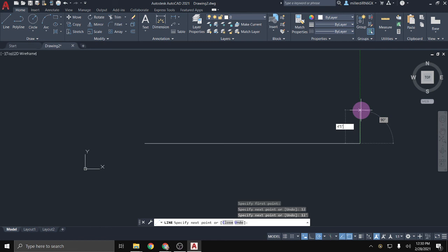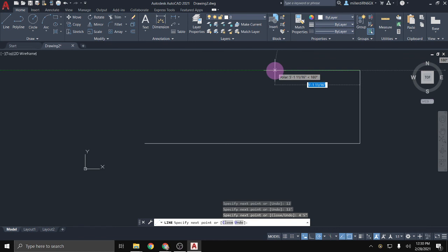So do not type in 2 singular apostrophes, because then it's going to highlight it red, because you just said 4 feet, 5 feet, feet. So it needs to be the quotation mark, or I could just type in 4 feet, 5 without any unit annotation after it, and it is going to infer that the 5 means inches.